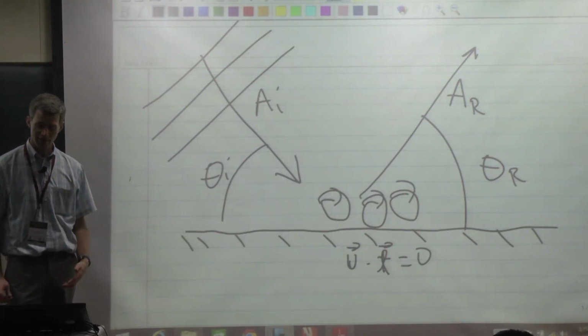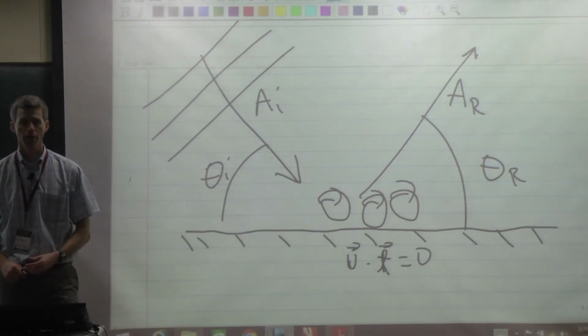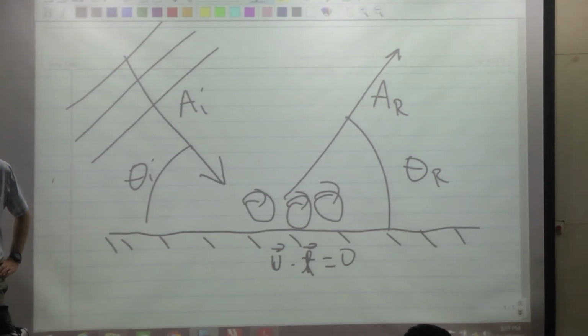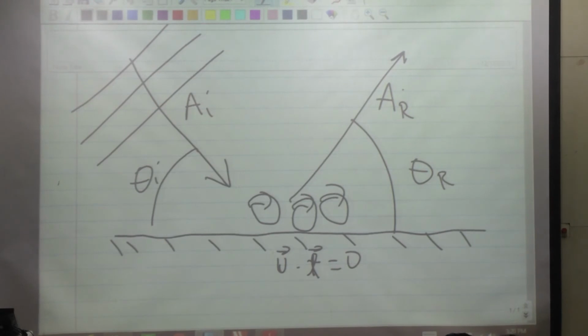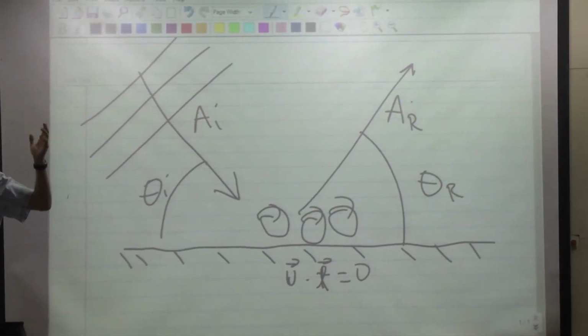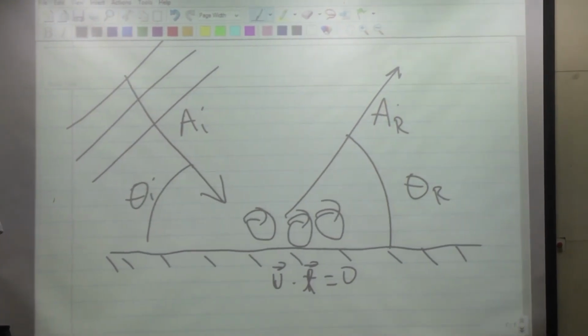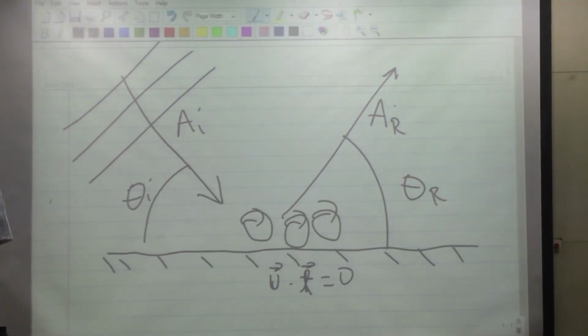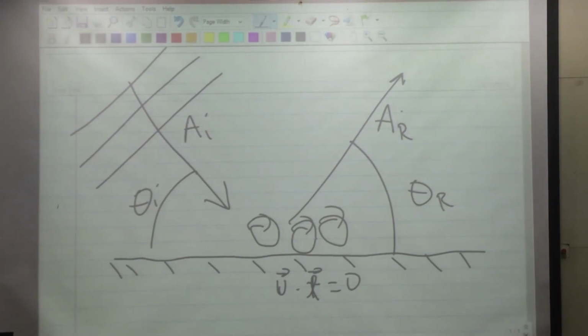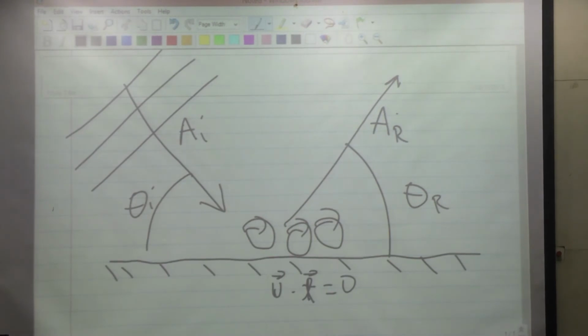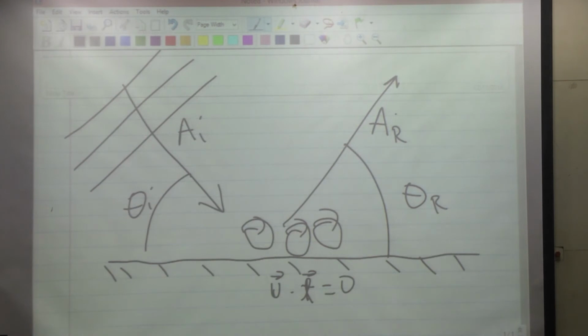All right? And so another way of saying this is that the acoustic wave is damped because of the no-slip boundary condition, because what happens is that you have a certain amount of energy in the incident acoustic wave. Some of that energy is in the reflected wave, but also some of it is put into the vortical disturbance. So the reflected disturbance has a smaller amplitude than the incident disturbance because some of the energy in the incident wave went into the vortical disturbance. And so this is a common observation. If you look at acoustic textbooks, you'll find formulas for sound wave dissipation at walls. Well, the energy isn't going poof into the ether. The energy is just getting transferred from one disturbance mode to another. So the wall provides a mechanism for the conversion of irrotational, compressible kinetic energy getting transferred into kinetic energy that is rotational and incompressible, the vortical disturbance.